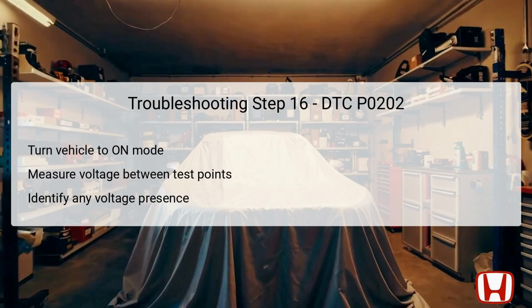If you detect voltage, further actions will need to be taken to repair that short within the wiring, impacting the relationship between the injector and the control module. However, if there is no voltage, the issue resides elsewhere, necessitating additional diagnostics.